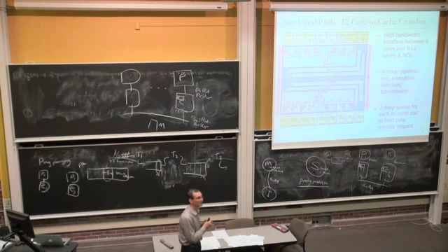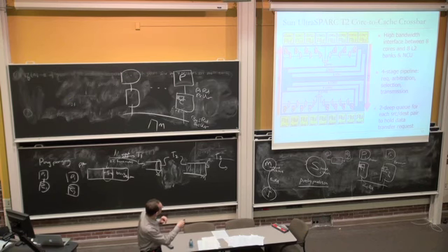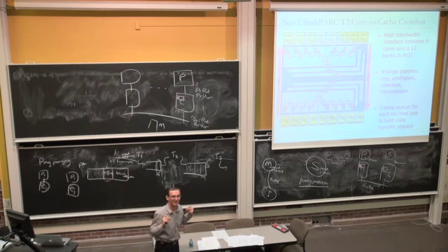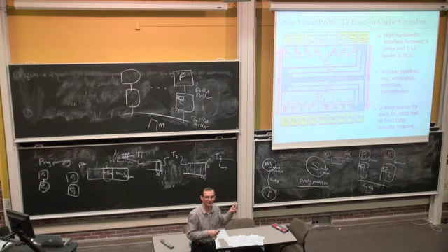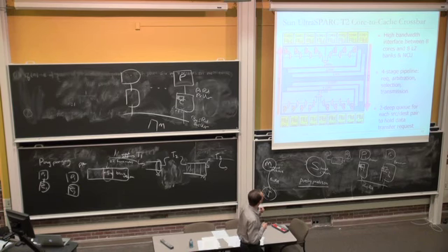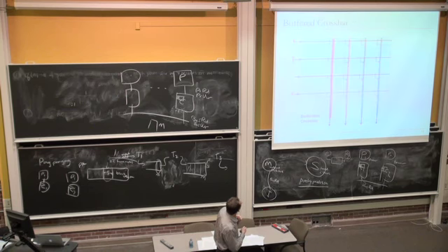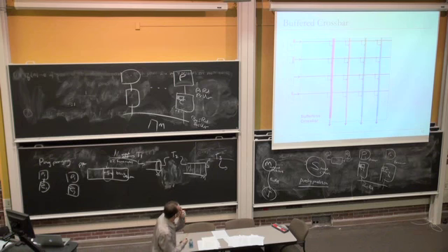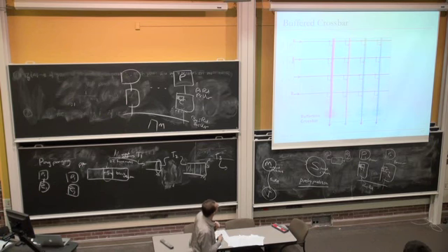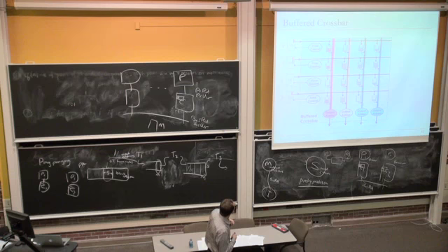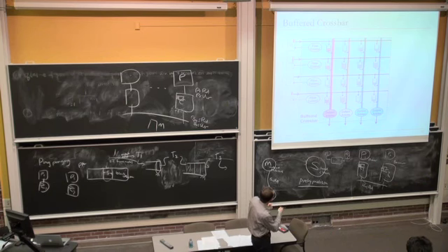If you look at the power consumption numbers of these chips, this Crossbar does consume a lot of power because it has all the circuitry and all these connections. That's why this kind of Crossbar is not used in many other processors, or more cost-effective processors, if you will. Okay. So there are other ways of designing the Crossbar. This is a bufferless Crossbar. These are the switches, and you need to arbitrate for the switches. But you could make the bandwidth better in the Crossbar by adding buffering, right? You could also make the switching more flexible.